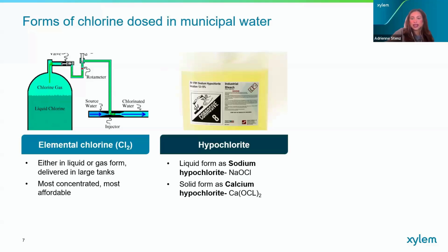Chlorine can also be dosed in a liquid form of sodium hypochlorite, also commonly called liquid bleach, which is commercially available in strengths of approximately 15% by weight. This can be added by chemical metering pump or by physically dumping it.